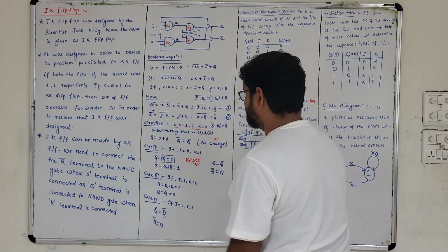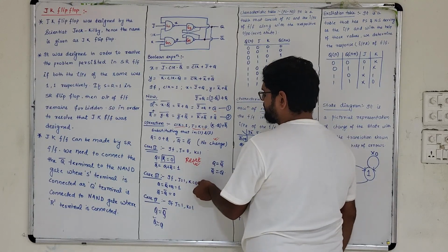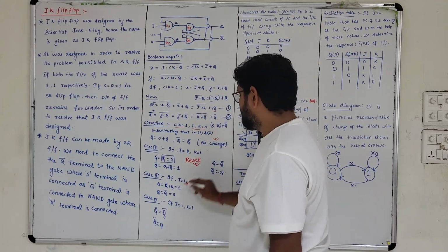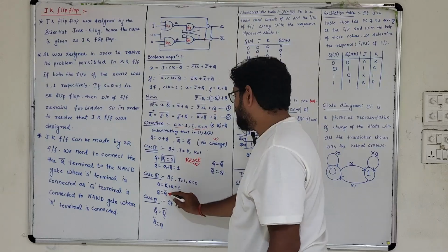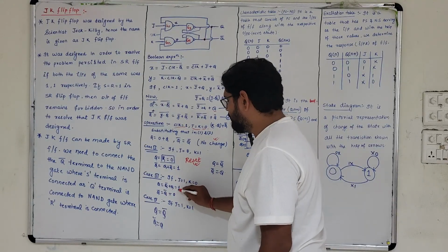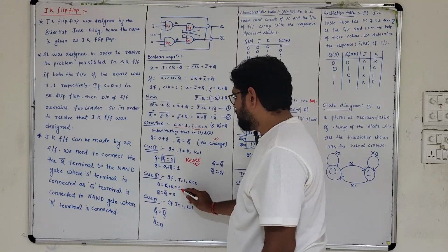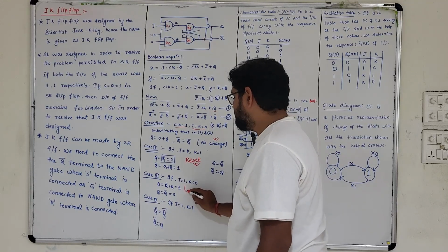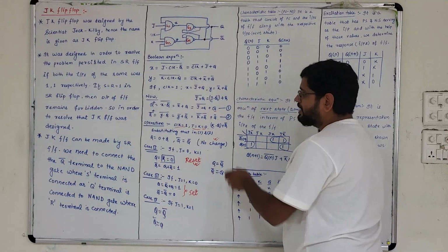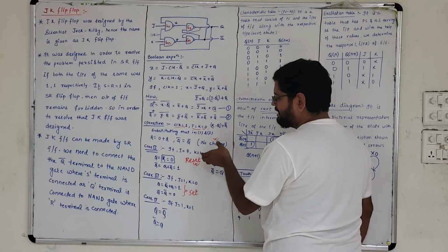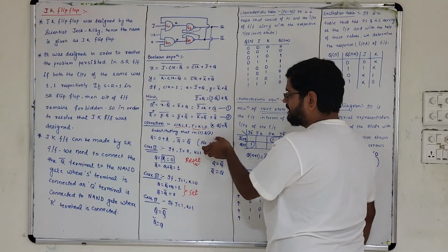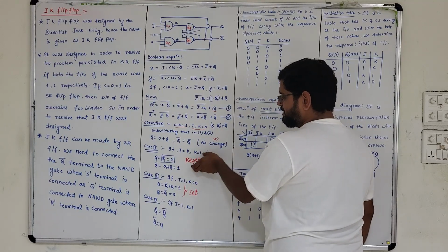After getting the reset condition, the next is J equals 1 and K equals 0. Go on putting in the values, and you will get Q equals 1 and Q bar equals Q bar, which is nothing but the complement of Q. We have got the value of Q equals 1, and therefore the complement of that one will be 0, and this condition will serve as the set condition. Now you can clearly visualize that we don't have any change in the operation of the JK flip-flop compared with the SR flip-flop. We are getting the same thing: no change, reset and set.